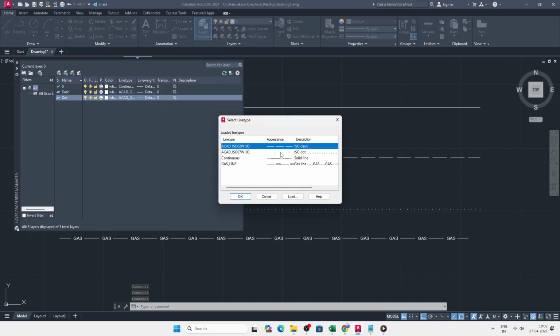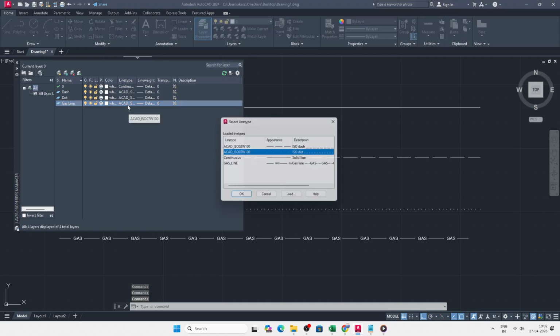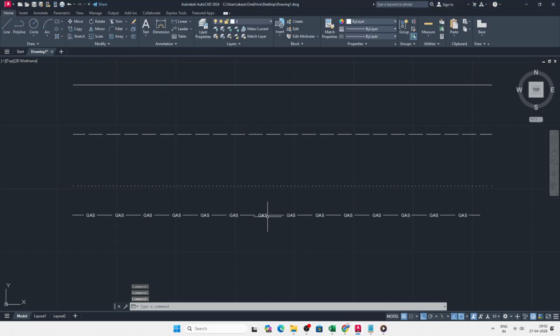If your dashed or complex lines look solid, that's a scaling issue, not a broken linetype. Use LTSCALE to control the global spacing of all linetypes in the drawing. Increasing LTSCALE makes dashes and gaps longer. Decreasing it makes them tighter. After adjusting, check a few typical objects to confirm the pattern reads clearly at your drawing scale.